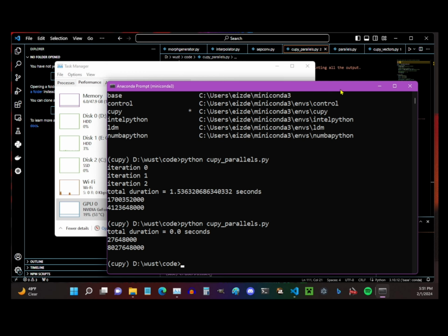So when you're doing it with the CPU, you're writing to the main memory from the CPU, and the bus is not as wide. If the bus is not as wide, it can't move data as quickly. What is a bus? Well, it's an electrical line. If you have an 8-bit computer with 8-bit memory addressing, you have 8 wires operating in parallel that go to memory, that literally go to pins on the CPU and then connect to pins on a memory chip.